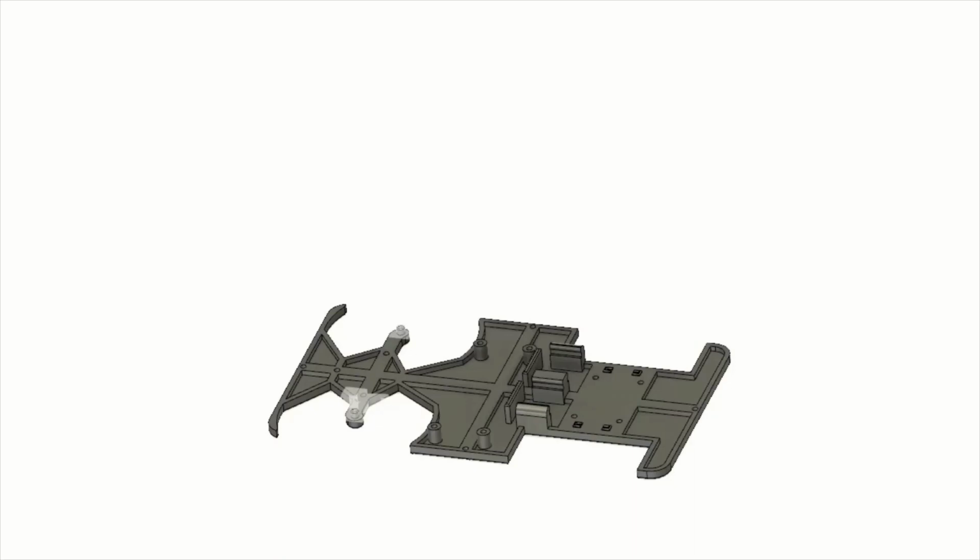As mentioned before, I wanted to achieve a small steering radius for tight turns. It was crucial to ensure that the front wheels had enough space to move, and the steering geometry was designed accordingly. I found the best place for the servo right on top of the front axle.